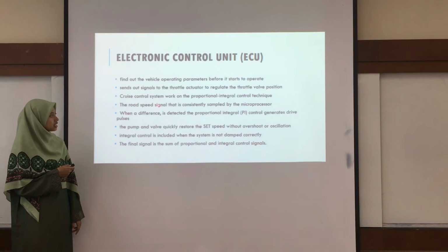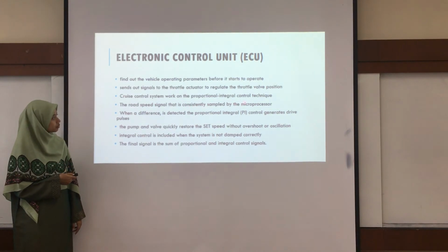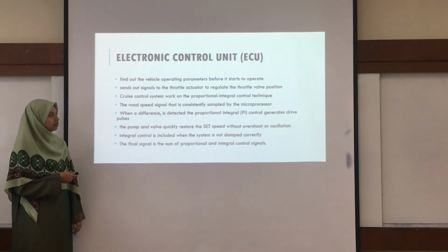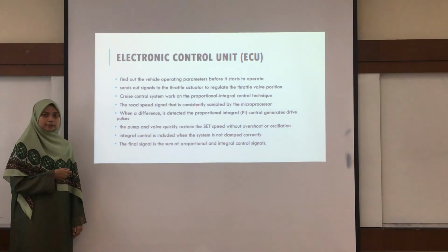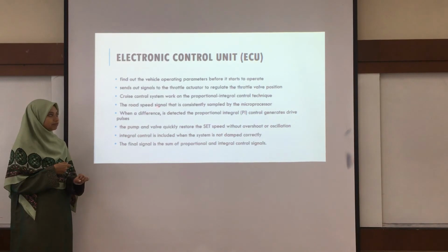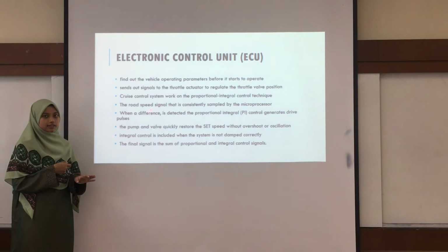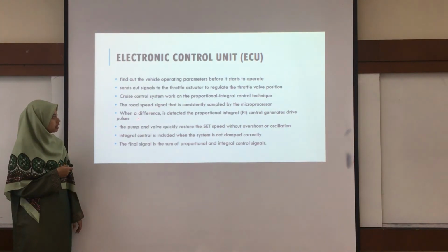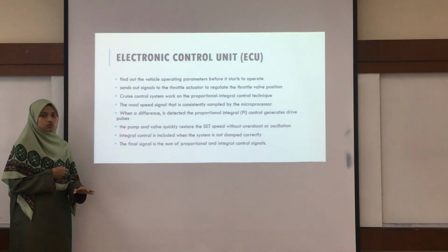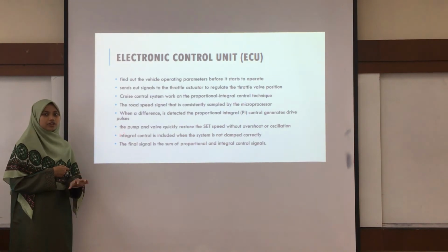The road speed signal is consistently sampled by the microprocessor, which means that the microprocessor will consistently record the speed of the system, and then when a difference is detected, the proportional integral control generates drive pulses in order to make the responding variable zero difference with the set point.